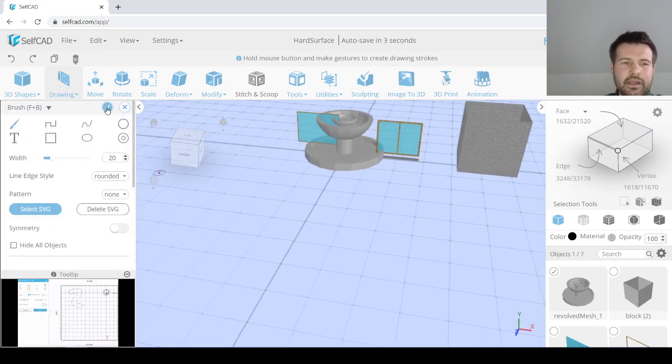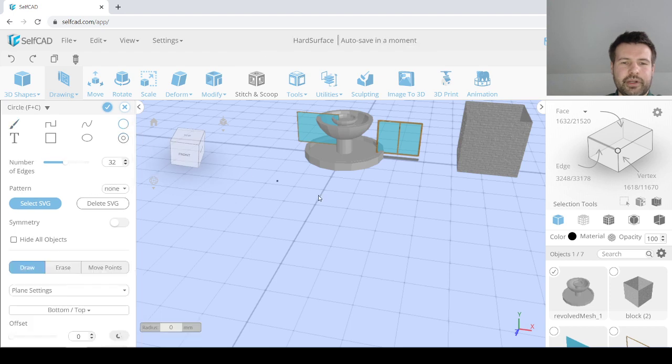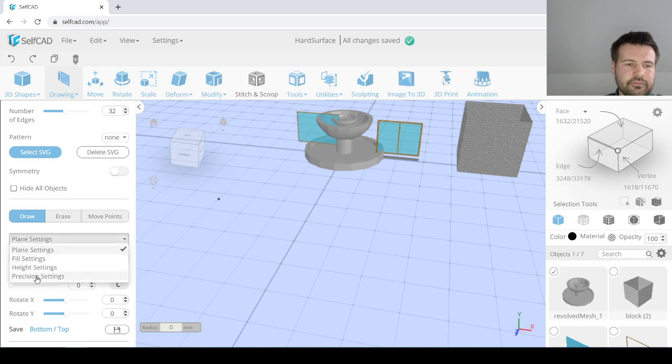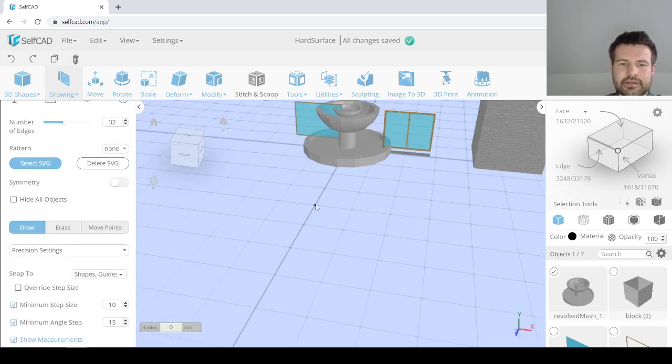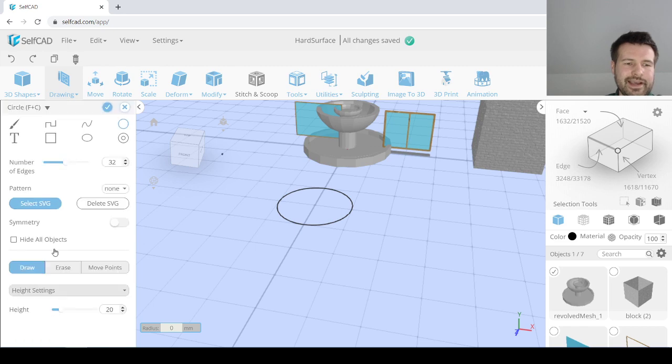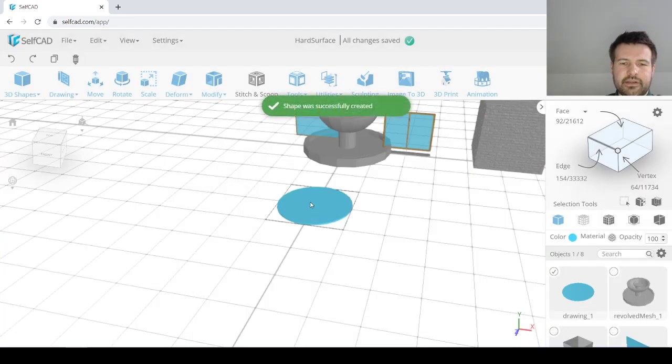Freehand will already convert to a 3D shape when I finalize. So you just need to generate a circle and then align it and scale. So we're just going to do this, and the setting that I want to change is height, and put like 2. It doesn't have to be anything big.